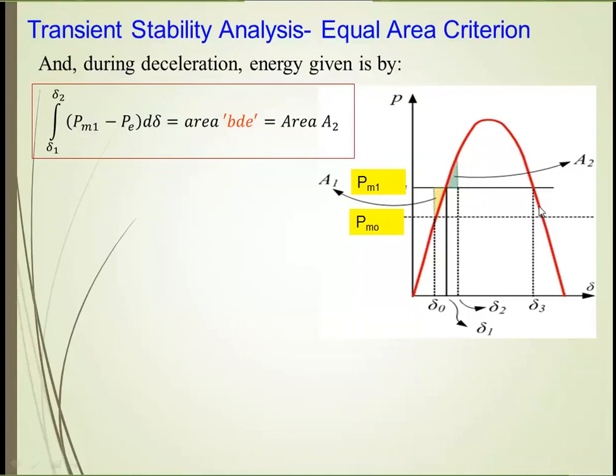So when we have this, the rotor angle is much larger. Rotor angle delta 2 has increased to this point here. In that case, PE is less than PM. But beyond this point, which is another operating point, PE will drop to zero. And that means the generator will lose synchronism with the system, that means with the load, with the line actually.